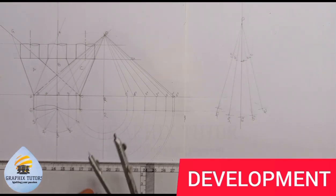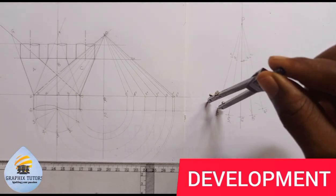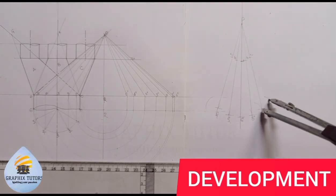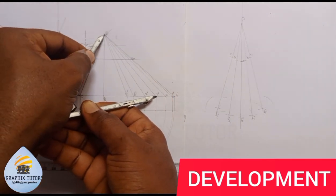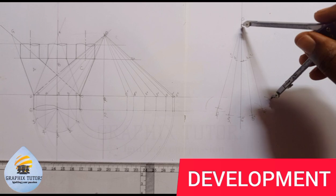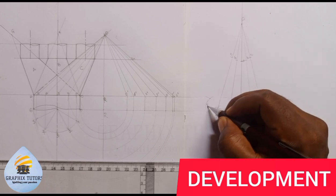Right? I'll come again, take the measurement 0 and 1. I'll come to the line of 4, this point. I'll mark to the left, and I'll come here and mark to the right. Right? So I'll come from 0 to 3 now. I'll place it on the point of P and I'll mark 3 here and 3 here. So that will be my point 3. So this will be 3 prime and here will be 3 prime.